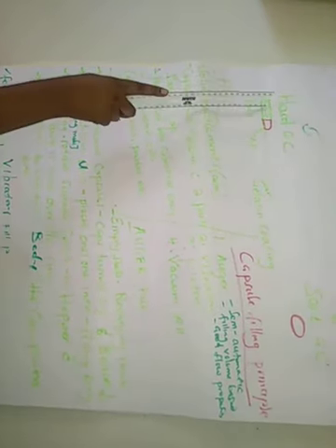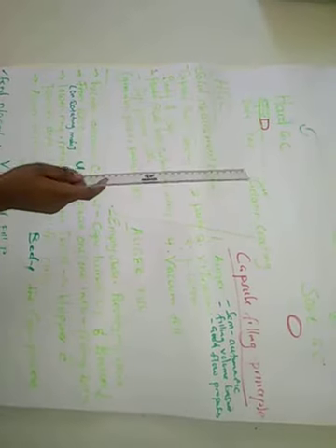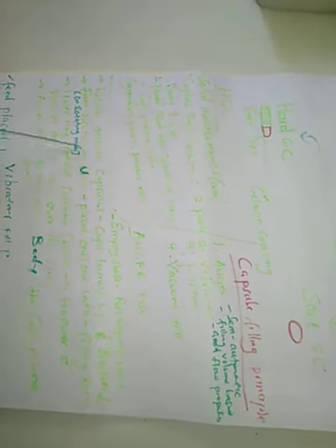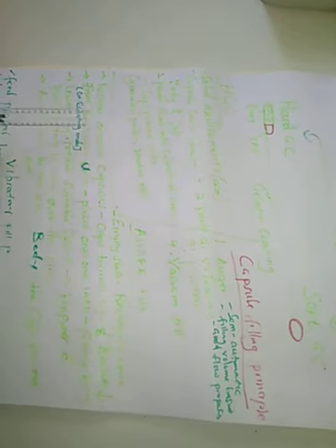The function of the rectifying unit is to rectify both the body and the cap into a position which enables filling of the body, and then joining using the cap after the filling is done. It descends the capsules in such a way that the caps are turned upwards and the bodies are turned downwards.